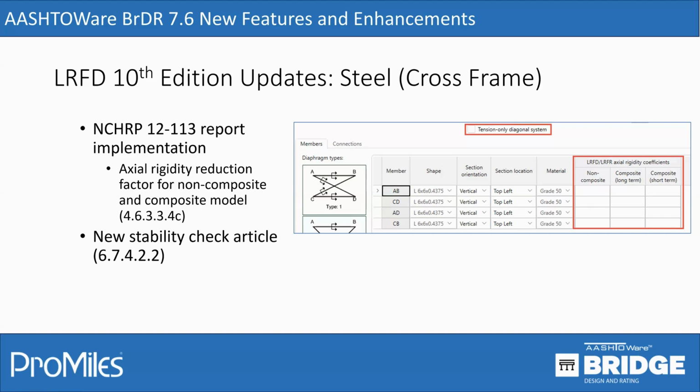One thing to note here is that these coefficients in the specs were recommended for T and angle sections, but based on the implementation, if the section is not a T or angle section but you have entered the axial rigidity coefficient, it will get used in the analysis as well.